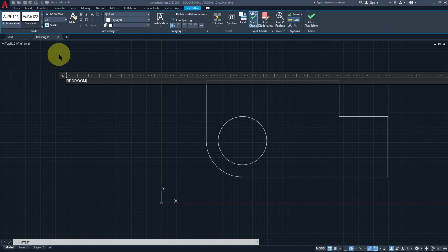So how do we change the font size so that it is visible in our drawing? Most of our dimensions involve 1,000, by 1,000, because it's a building. So probably let's just say we set the size to 300. Enter. You need to press enter to accept that size.